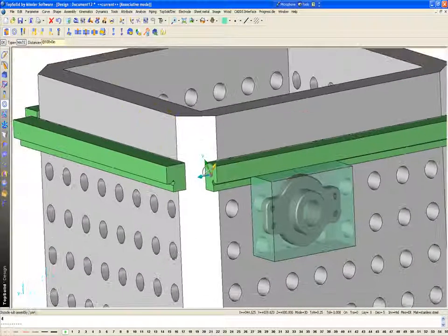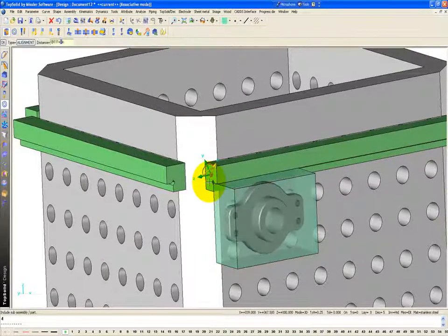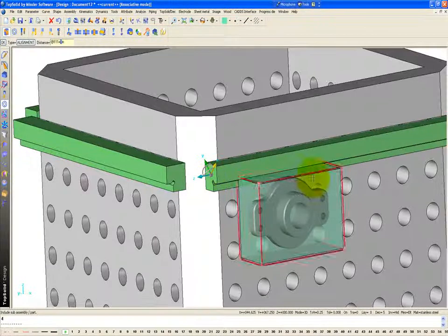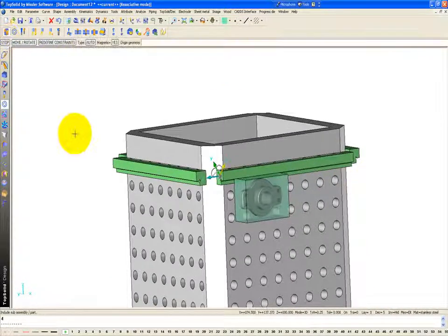Alright, I'm going to say OK, and I'm going to take this face to the outside of my fixture bar here, but offset it 1 inch in. And like that, I'm going to simply say OK. I'm going to say stop, and here I'm not going to make a pattern. Eventually I will make a pattern, but I'd rather make that inside of TopSolid'Cam after I create all the machining I need for this part.